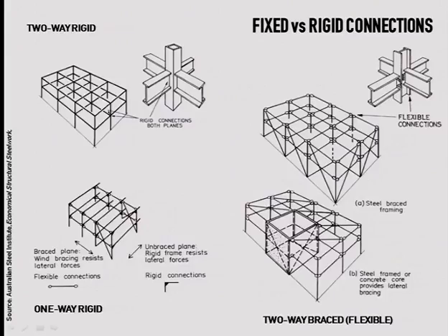When we have bolts, generally one axis is still released. It's not fixed. It's not constrained, and therefore the element is able to rotate slightly about the axis. So we can't talk about a rigid connection. And in that case, the solution is that we need to brace the structure so that we can actually control lateral stability. With a rigid connection, there is a little bit of that taken into account by the joint. So that's the main thing.